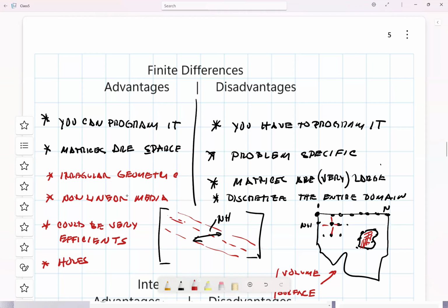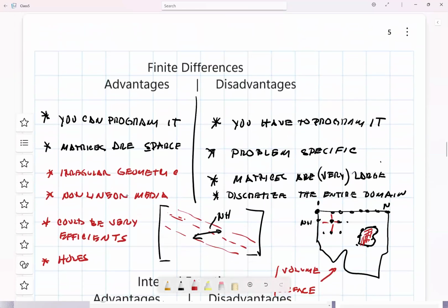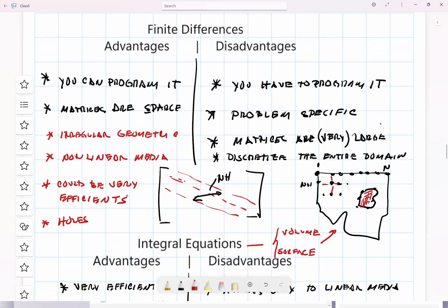But I remember that Comsol, for time domain, uses the differential method that you showed in the previous slides. Finite differences, yeah. I know that finite element methods, I mean, this Comsol uses finite differences for the time domain changes. Yes, it's something similar to EMTP, where we integrate in time. So if you need to go with time, you need to do something with it. Finite elements themselves don't discretize the time, they discretize the space.